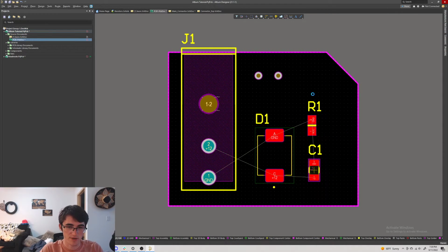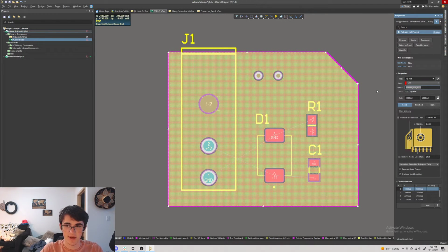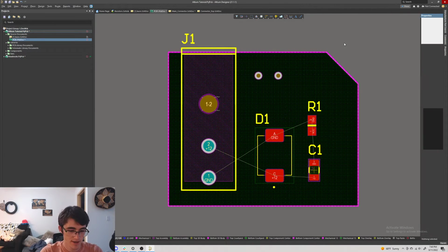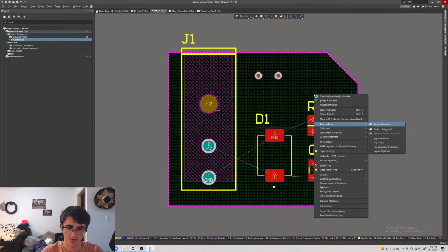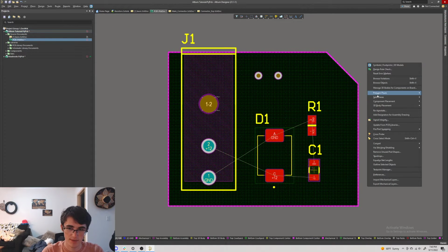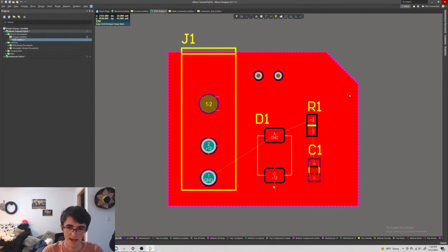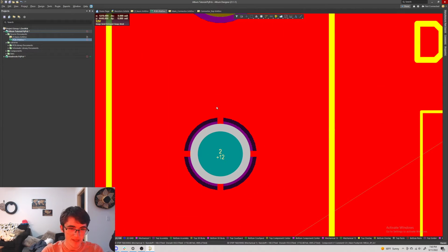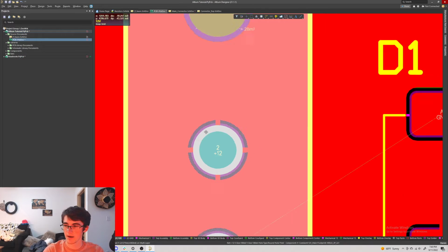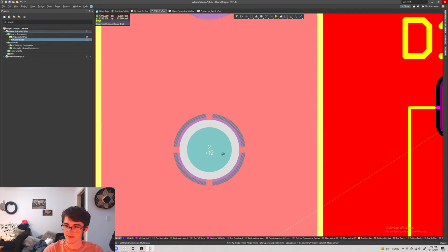So what we want to do is bring it back, and double click this plane. You can see here, oh, it's on the 12 volt layer, but we haven't designated what net or what power line it's connected to. So we want to connect it to that plus 12 volt line. You'll see here that it's going to want to regenerate again. So we press T, D, and then A to regenerate it. And now you can see that it's connected to this Megafit connector through these lines here.